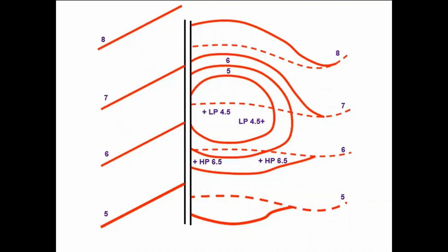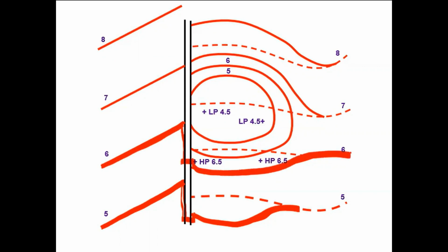So let's clean this up and go over it again, because it's an important point that we need you to understand. Your 5 contour is just going to run across the parking lot. It's going to then run along the face of the curb, cross over, attach into the 5, and go off just as it did before. The 6 contour, same thing, runs across the parking lot, comes down, crosses over the curb, and attaches into the 6 as needed.